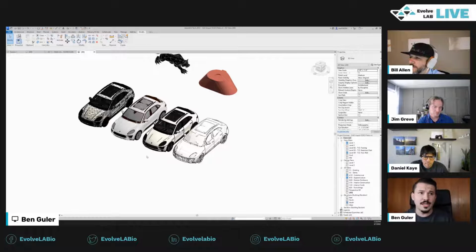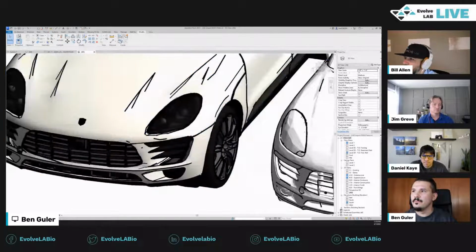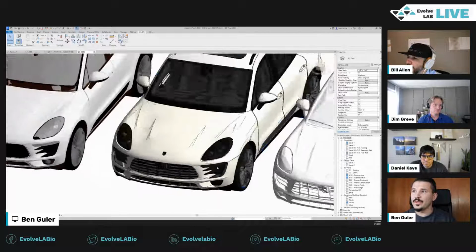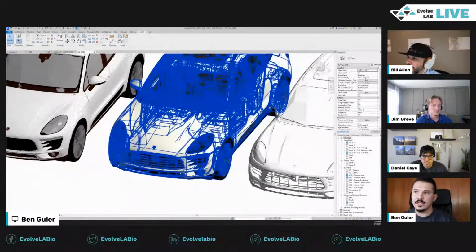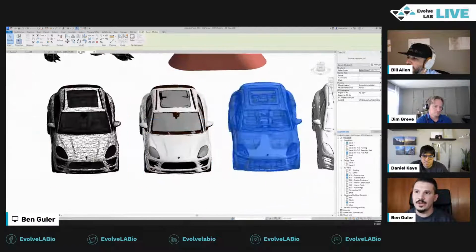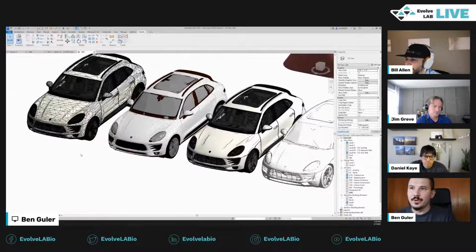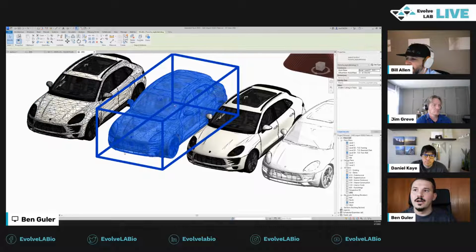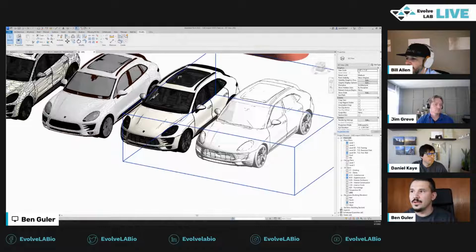But if you do use the OBJ importer, you can get a really nice smoothed mesh without the mesh lines in there, which looks really good, a lot better than what they used to offer. Unfortunately, it doesn't work with the DWG or DXF or SketchUp importer. We've built something like this using our product to do that using DXF.